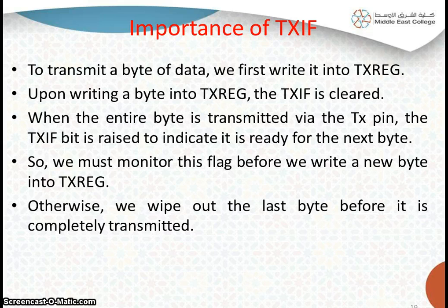What is the importance of the TXIF flag? We have understood that the data which we have to transmit first has to be placed in the TXREG. As soon as we place the data in the TXREG, the TXIF is cleared. That means the data is sitting in the TXREG and is not yet transmitted.